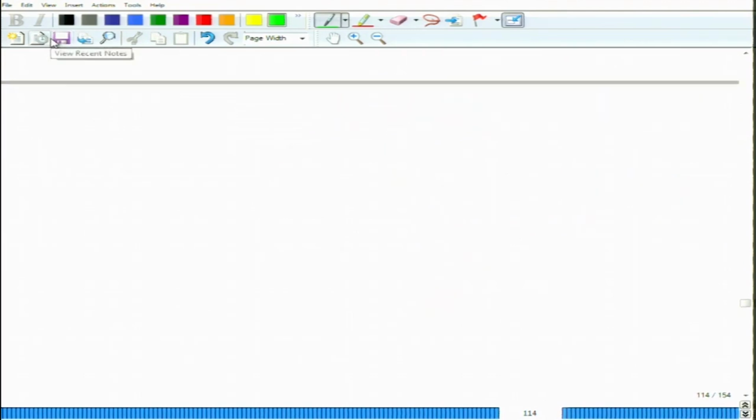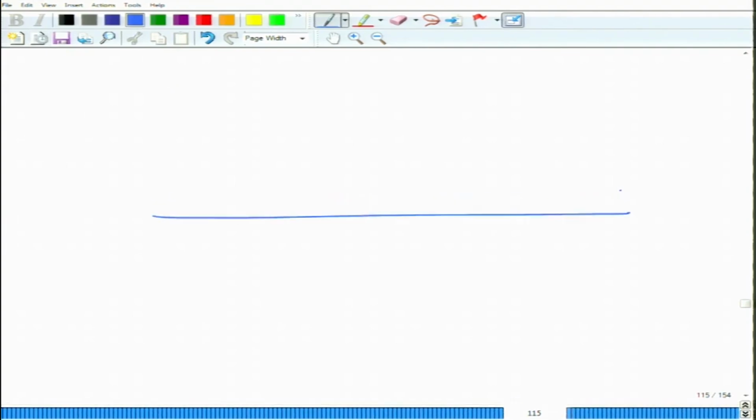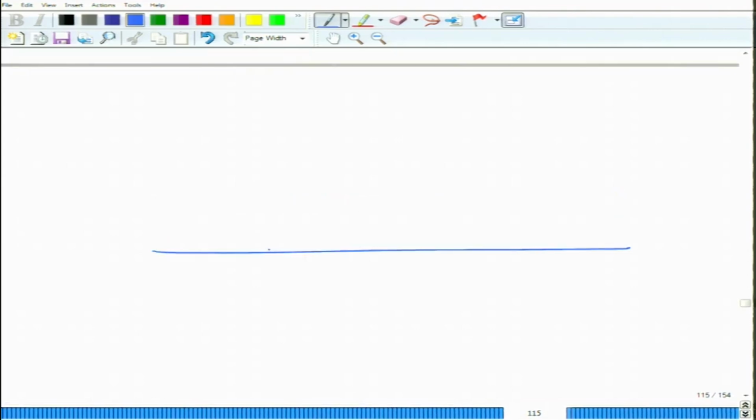Okay. So, I am going to plot the Bode plot, and the Bode plot is best plotted on a log axis. So, what we are going to do is, rather than conventionally plot it on a linear axis, we are going to plot on a log axis, because it varies logarithmically in omega. So, on a log axis, you can see that every decade occupies a single unit.